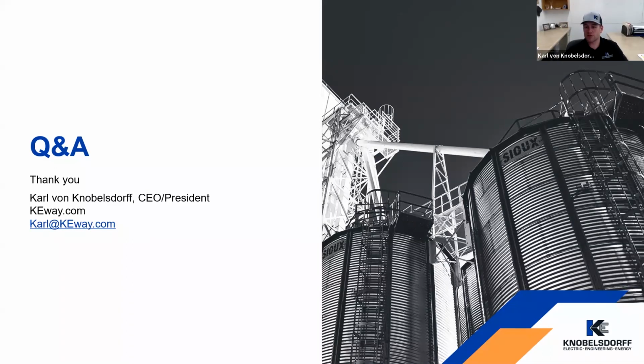Yes, we do. So an arc flash assessment involves, again, if you've never done an arc flash or short circuit study at your facility, basically we come in and we go top to bottom in your facility. We start with the utility. We have to get the incident energy information from them. And then we model your entire facility down to the last piece of equipment. So we collect all the breaker and fuse information. We collect all of your conductor information, including size and length, and all the panel boards, transformers, everything that's going to need a label to meet NFPA 70 requirements.